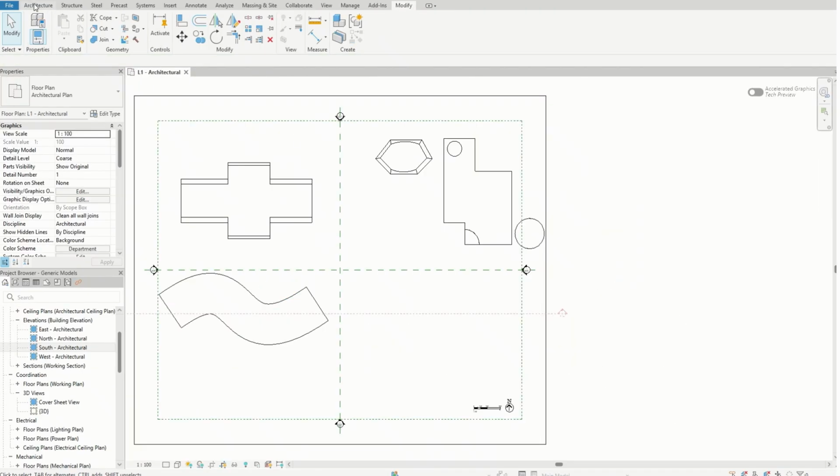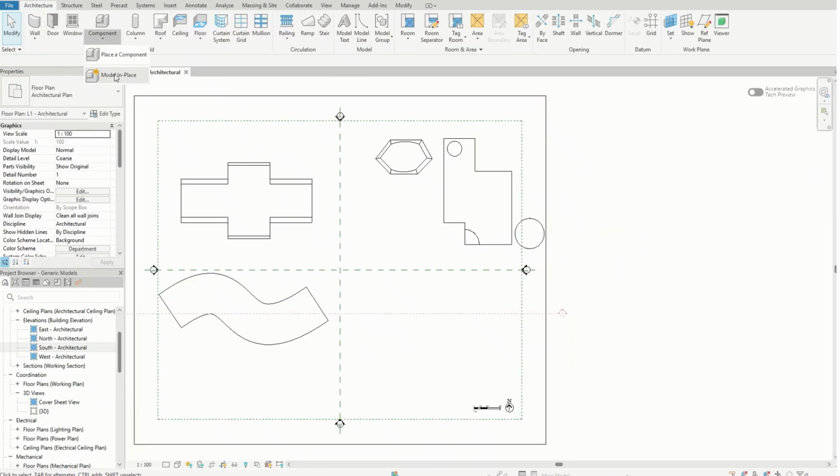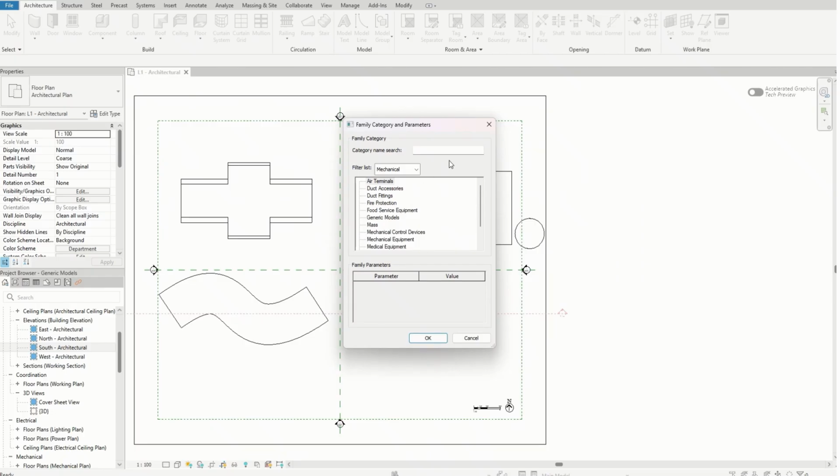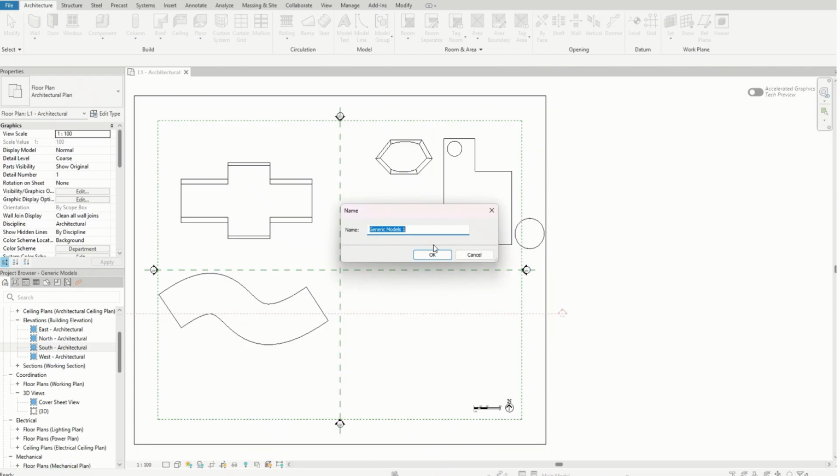Part E. Swept Blend. Steps 50 to 65. Step 50 to 53. Start and choose tool. On level 0, clear or move previous forms. Start Model. In place, choose generic models, accept the name and pick Swept Blend.